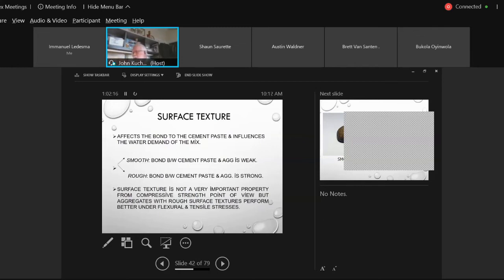Nowadays, if you cannot design a 32 MPa mix minimum, say to meet the City of Winnipeg pavement criteria, get out of the business. You've got no right being in the ready-mix business. It's not rocket science. There are more important factors than strength that are more critical: abrasion resistance, durability, freeze-thaw resistance. Get my drift? So strength is not key.